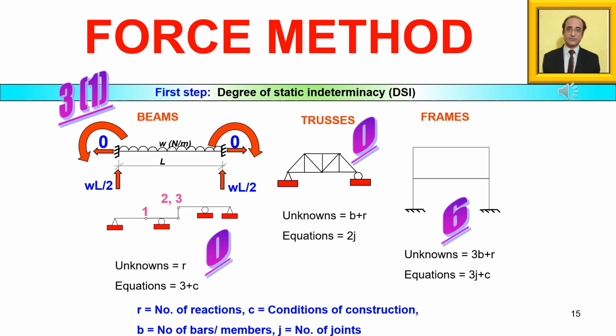So at the first hinge, moment is 0. At the second location where there is a vertical link element connecting the two substructures, there are 2 conditions, that is no bending moment can transfer and no axial force can transfer. So if you input here the values, the answer comes out to be 0, and then you inspect whether the structure has any case of geometrical instability. If you inspect it properly, you will find that there is no such case, hence the structure is stable and determinate.